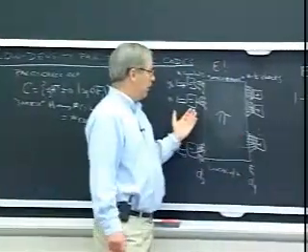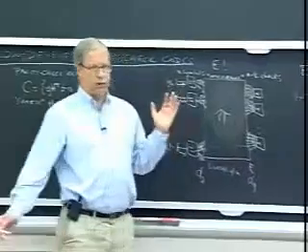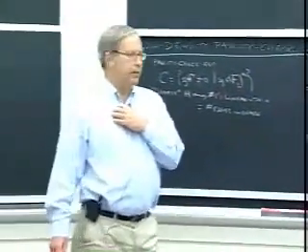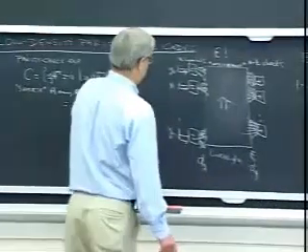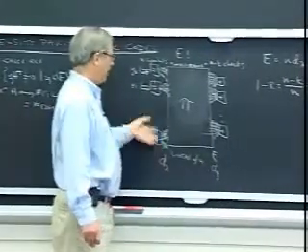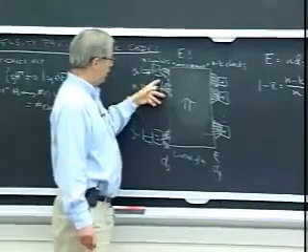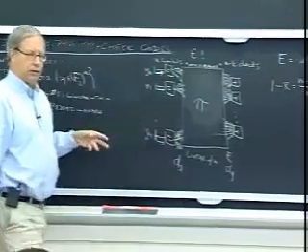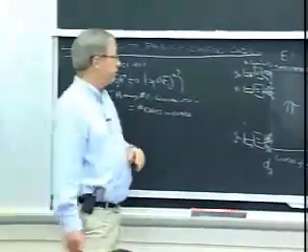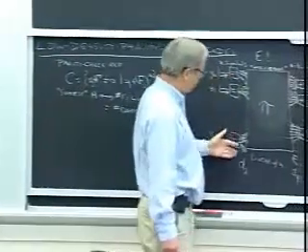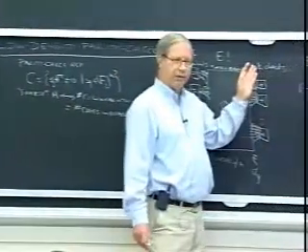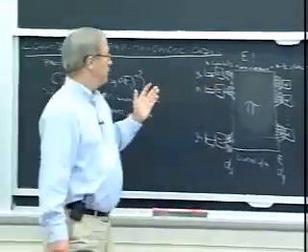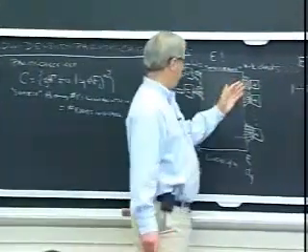So you do that. When do you stop? A very popular stopping rule is to stop as soon as you've got, if you made hard decisions on the basis of all these messages, that would give you binary values. And if all those binary values check at all these places, then that's a code word, or that's a trajectory that's consistent with a code word.